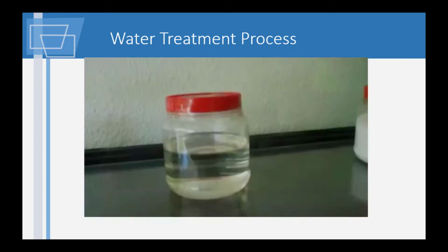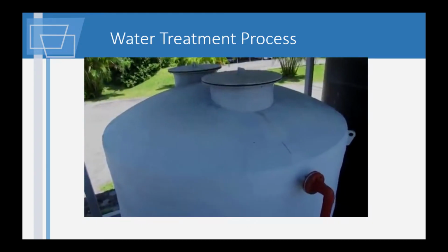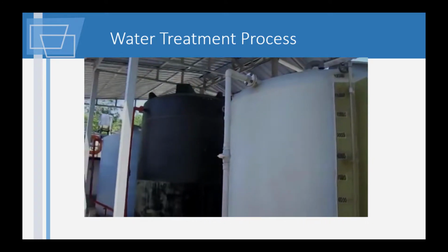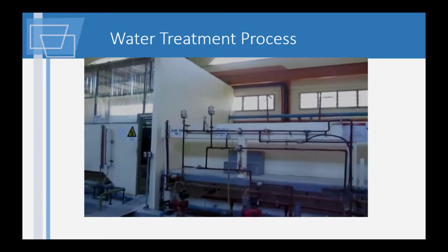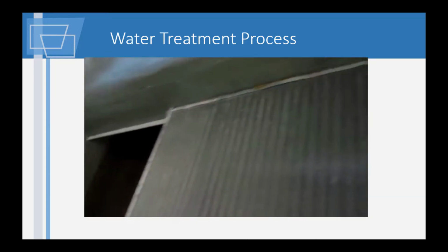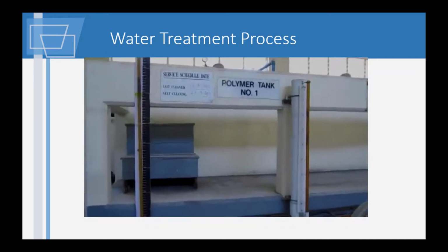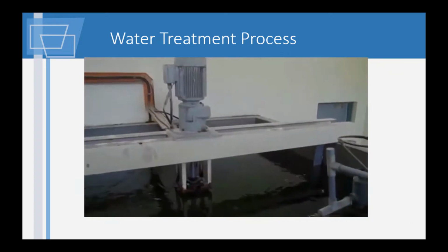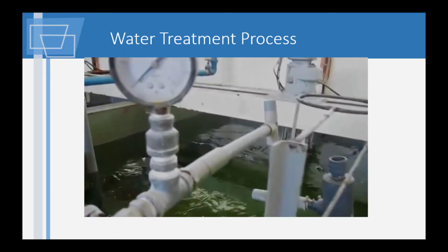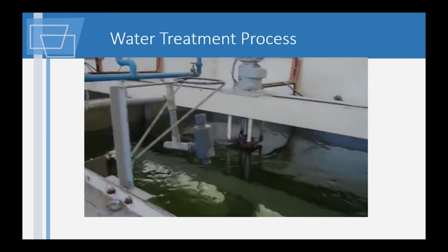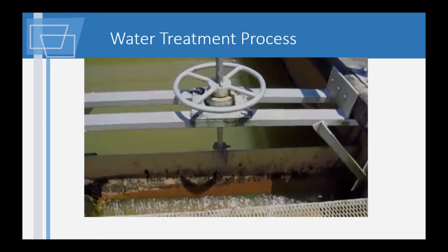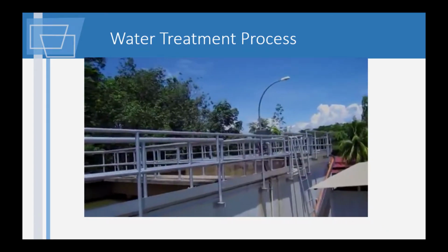Coagulants, usually alum, are added, leading to the formation of microscopic particles in water. This is followed by gentle agitation, causing small particles in the water to collide and combine to become bigger settleable flocs. All polymers used as flocculants in water treatment must be water-soluble, in water solution form. The active polymer in emulsion products is tightly coiled in droplets called micelles. These droplets are polymer emulsified in an oil phase.